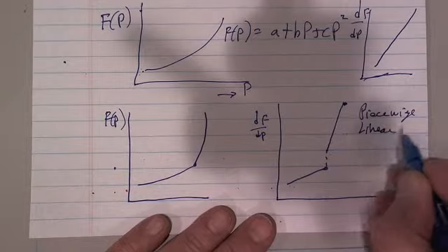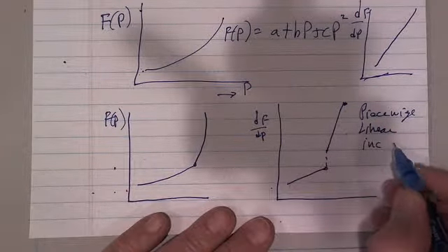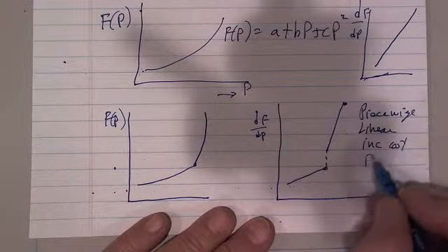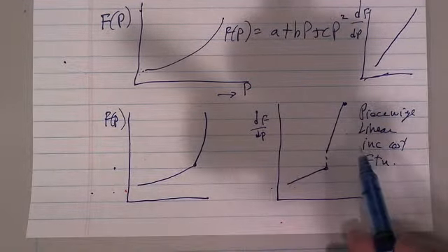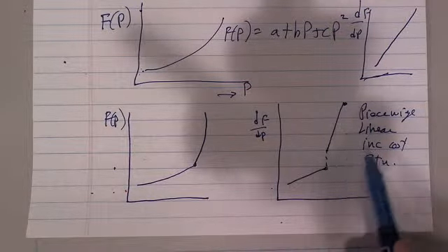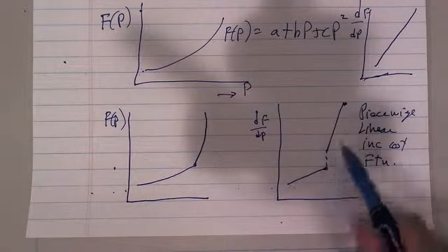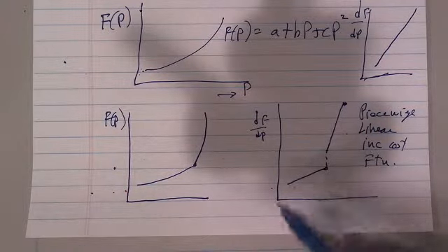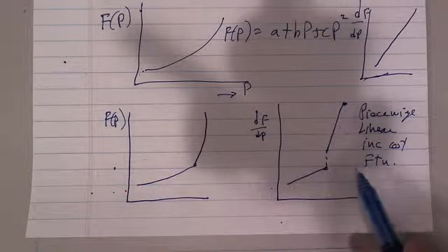Piecewise linear. Here we go, incremental or marginal cost function. Now, this might look a little exotic, but the way the power system operates, these slopes determine how the various units load up one versus the other.